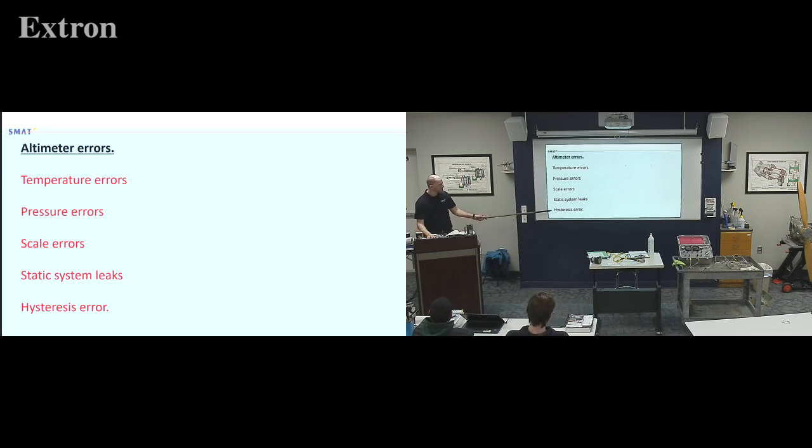That's one of the reasons you as an A&P are not going to be able to certify altimeters, is they have a lot tighter tolerances in how they're going to check your altimeter. They're going to bring it up, bring it down, bring it up, bring it down, leave it up, long time, bring it back down, long time, bring it up. They're going to move it all over and then they're going to check it, and it's just more than they want A&P mechanics to do.